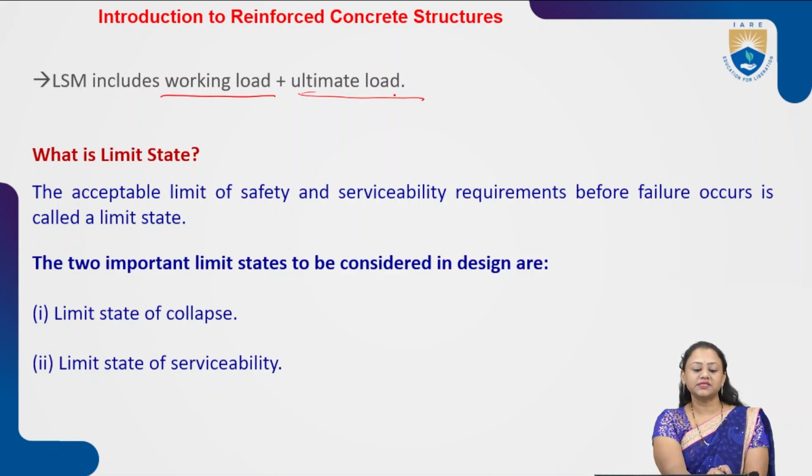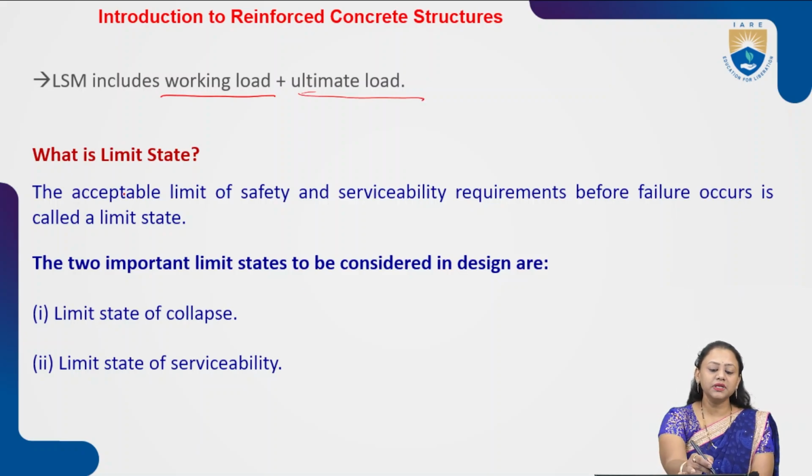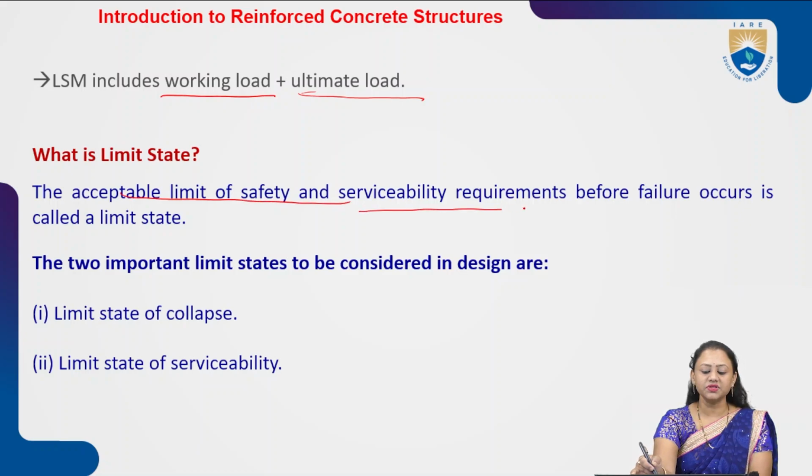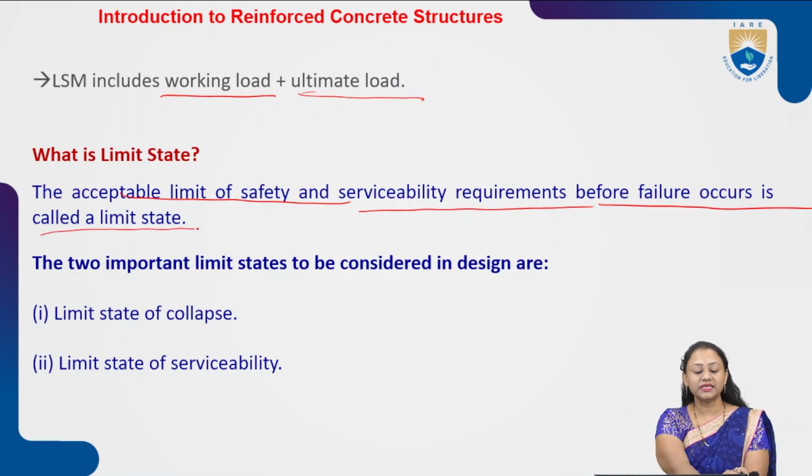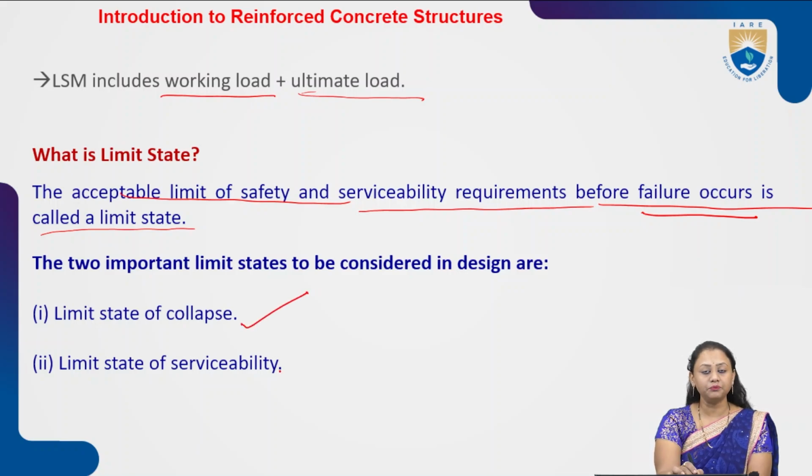So what is limit state? The acceptable limit of safety and serviceability requirements before failure occurs is called the limit state. The two important limit states to be considered in the design are the limit state of collapse and the limit state of serviceability.